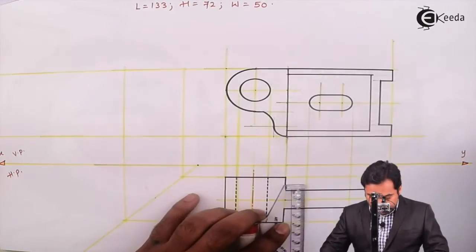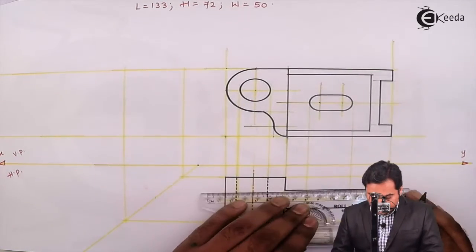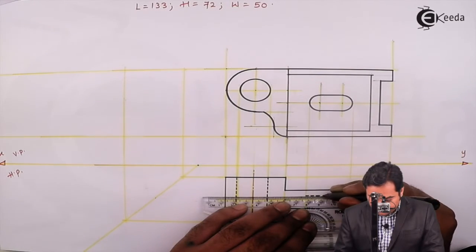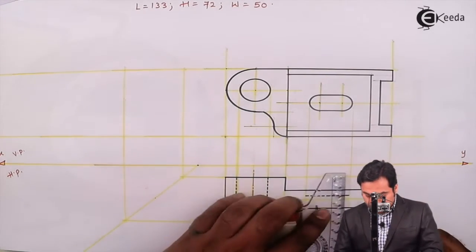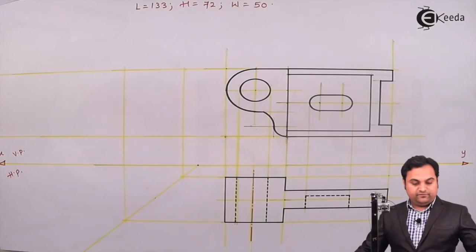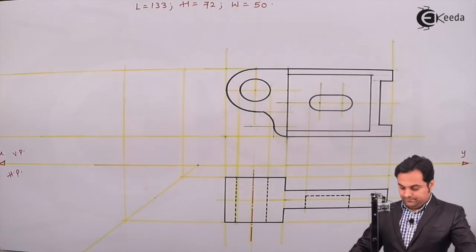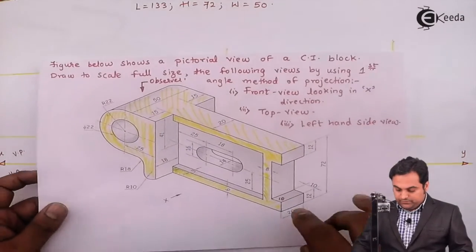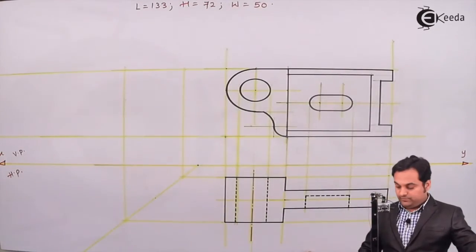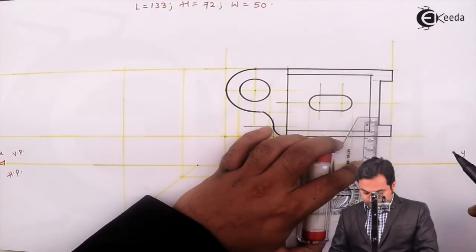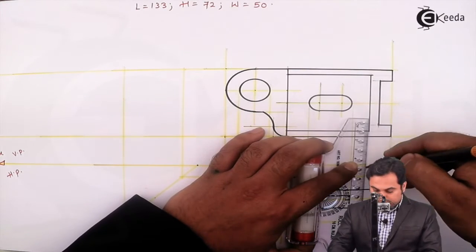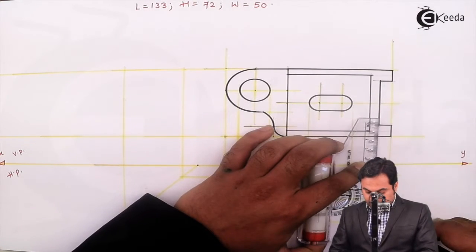Width is 14 mm. So this groove is not visible, that is hidden. And then from the top, this width, which is this line, is also not visible, so that should be hidden. Similarly, this line which is inside, that will also not be seen from the top.